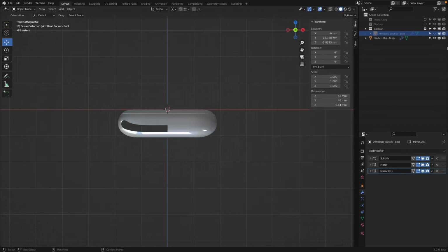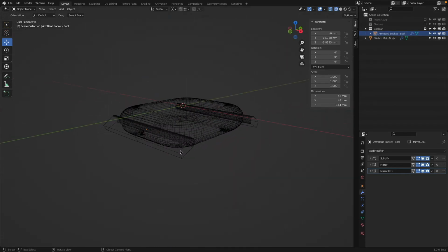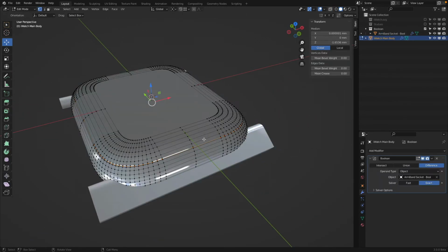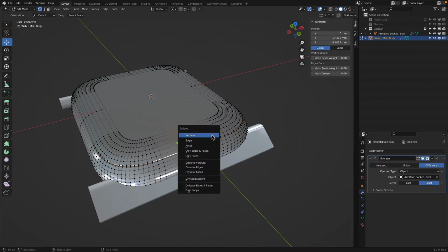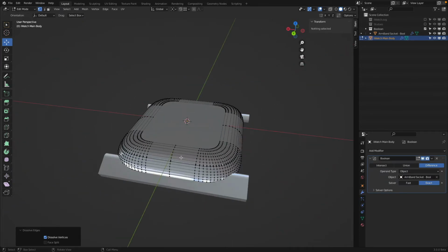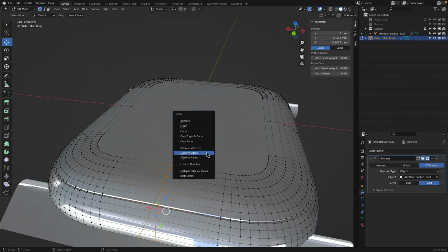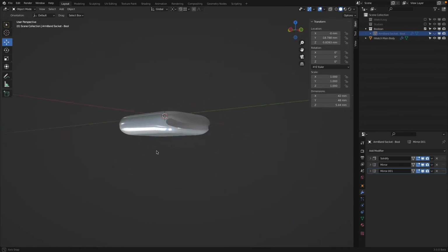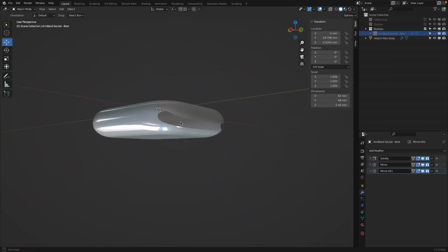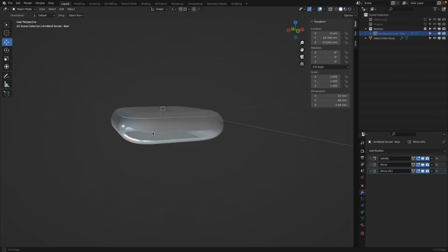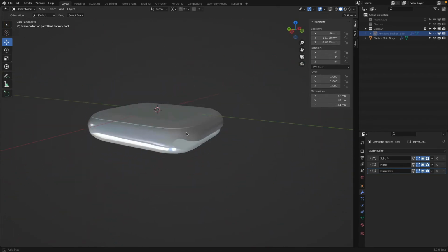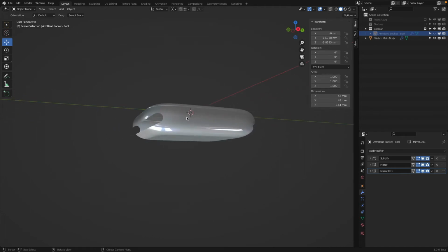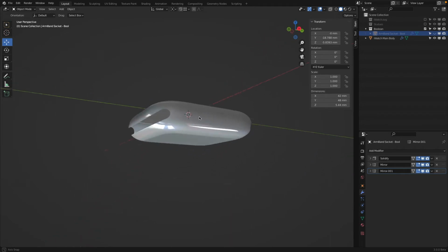We have a little bit of, I hate it when this happens, meshing issue. So let's see how we can fix this. I have already an idea where the problem is. I go to here, Alt click to this, dissolve edge, go to here, Alt click this edge, X and dissolve edge. No, that was not it, but yeah, partially it was. You can see something else is interesting now. So it did a trim, but this is not correct. I want the inside to be not open.